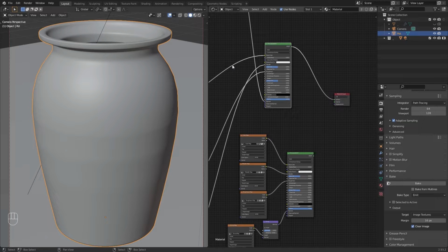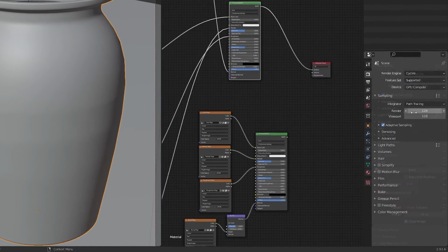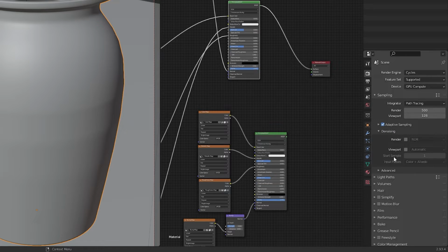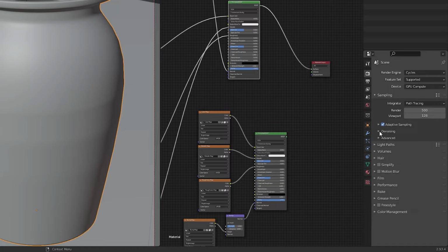These render settings are similar to the render settings we set for rendering this procedural material in the previous video. If you followed this session from the previous video, you can skip this section and move on to the next section. Now adjust the sample size here to 500. Here, by using adaptive sampling you can avoid taking render samples unnecessarily through the render process. For this, we do not use any render denoising here, to get the correct details of the materials.